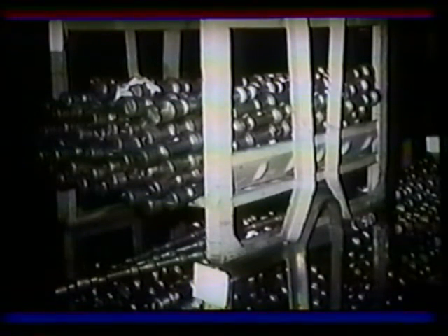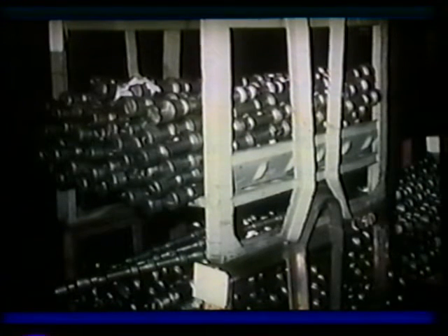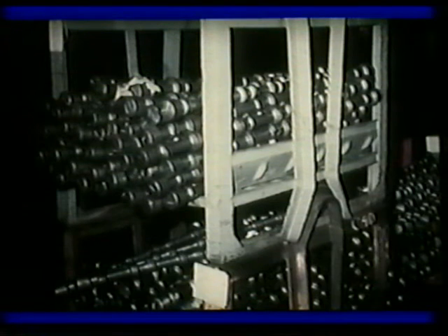Caterpillar camshafts are produced from forgings, castings, and bar stock. The determining factor in how a camshaft is manufactured is the amount of stress it is expected to withstand in normal operating conditions. Therefore, only our smaller 3200 and 3300 engines have cast camshafts, while 3400, 3500, and 3600 are forged. Recent innovations have allowed the 1.1 liter and 1.7 liter camshafts to be made from heat-treated bar stock with no interrupted cutting.